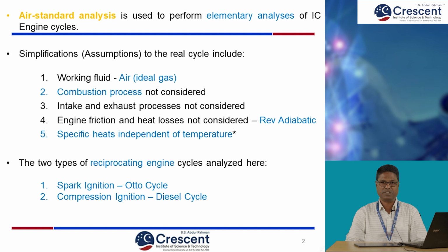We do this to make our analysis simple. The assumptions made when you go for air standard cycles are that the working fluid is essentially assumed to be air, which is taken as an ideal gas. The combustion process is not considered. Intake and exhaust processes are also not considered. Friction losses are also not considered, and specific heats are independent of temperature. So, based on these assumptions, we are proceeding with the cycle analysis.